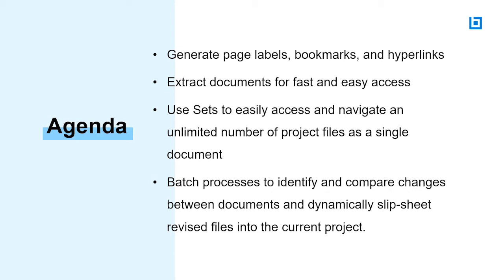Sets, you may or may not be aware of sets. A lot of people will get individual PDFs and then try to put them all together into one, which is pretty easy. You can insert PDFs into each other, but then you'll get an updated sheet, and then you have to figure out where to put that, and maybe you don't want to organize things all into one document. So sets will let you create a separate file that will sort of hyperlink to all of the individual PDFs and get them to behave as if they were a multi-page document. So I want to show you how that works as well.